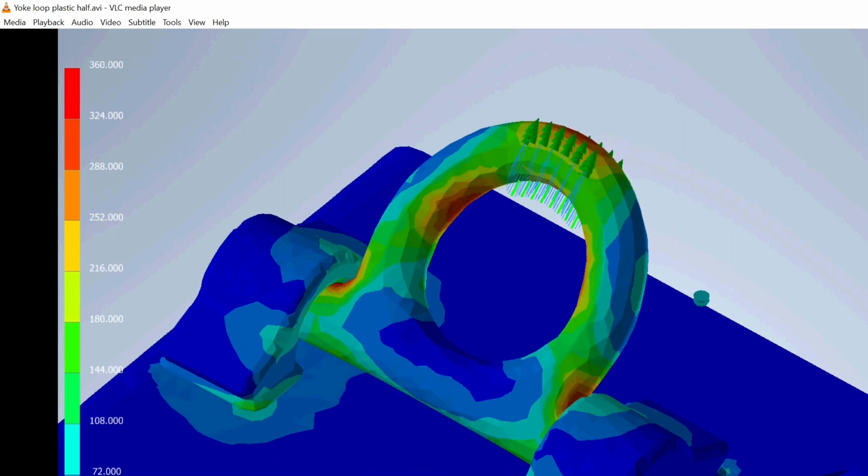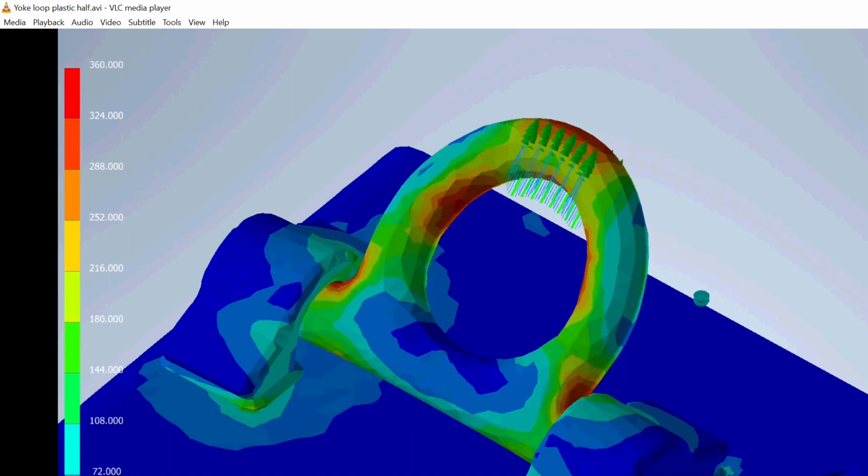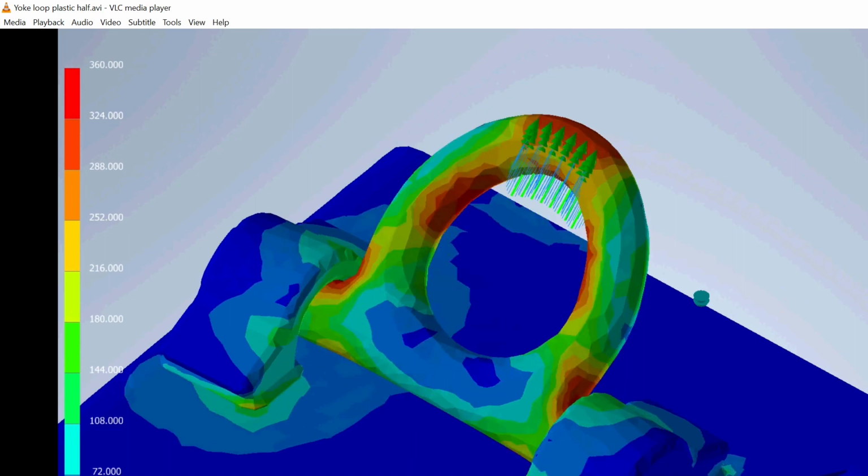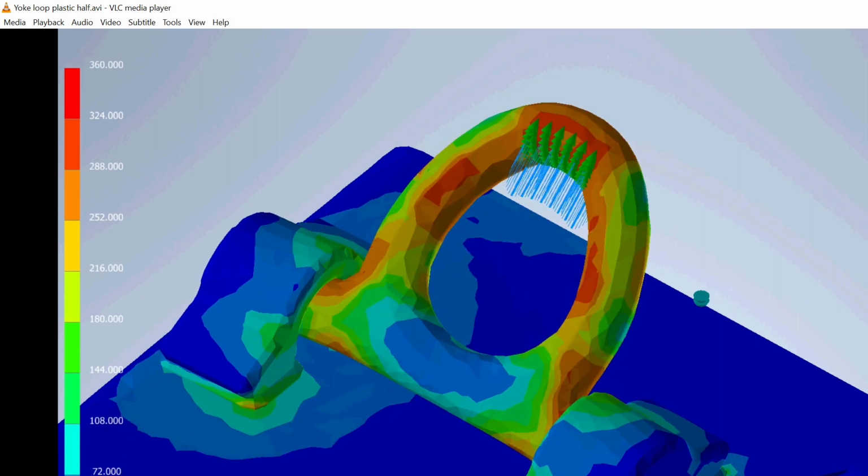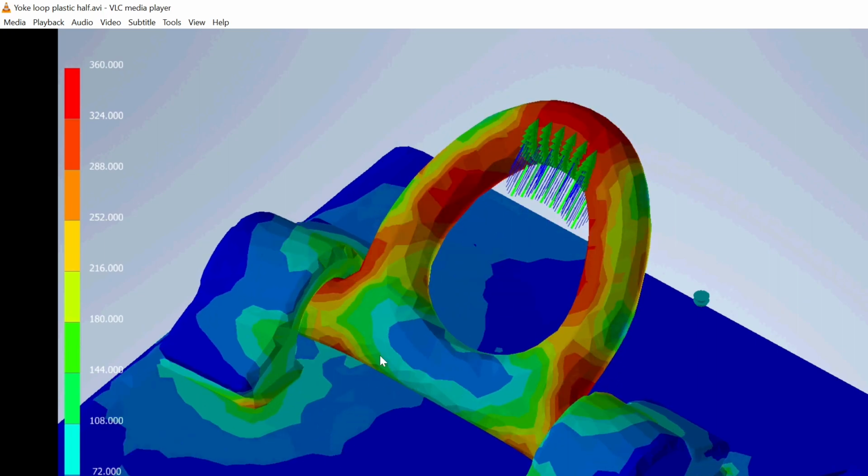So I had to draw the welds and the attachment points. And the conclusion of this analysis is that the component is not safe for when the load is full. You can see these red areas which are at risk of failure in a way. Now the loads are applied with safety coefficients based on Eurocodes, DNV, and what other standards you would like to apply, American, European, with local coefficients, with local annex perhaps.